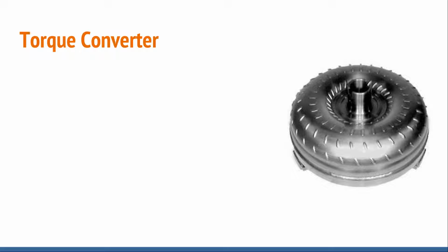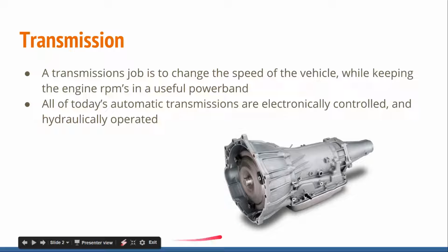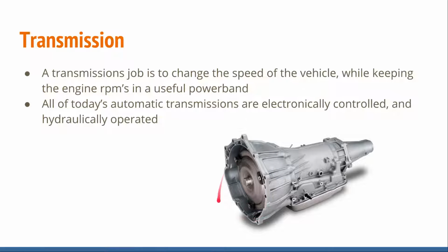So let's start talking about the torque converter. If you back up one slide, okay, the torque converter, right there. The torque converter sits in the front of the transmission. That connects to the flywheel or the flex plate of the transmission.